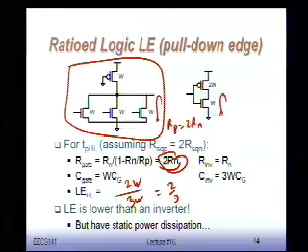But remember, static power dissipation. You're not going to use this for something which has 1 billion gates. If, however, there's a little circuit that you're really concerned about, it really has to be fast, throw a couple of those guys in there. It gets you some good performance and costs you some current, but that's okay if you only care about performance.